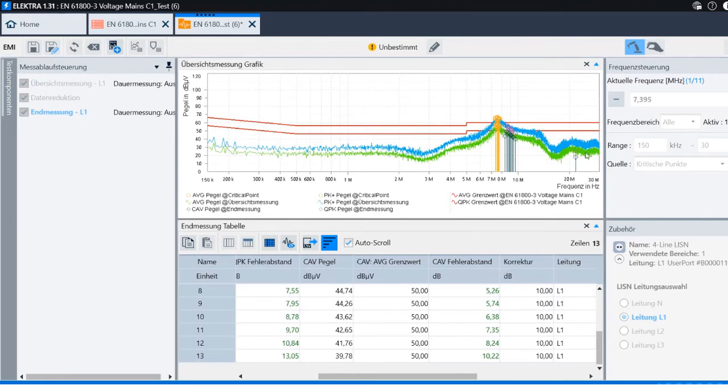So yeah, to understand this or to make a point here, in general, a shield is like a capacitor, which is close to the lines, the power lines, which are in the cable. And if you attach it to the different sides or not attach it to the different sides, then the capacitor is not formed properly and will induce even more problems in the higher switching frequencies. And if it's connected properly, it works like a small capacitor and will mitigate disturbances in the higher frequency range.